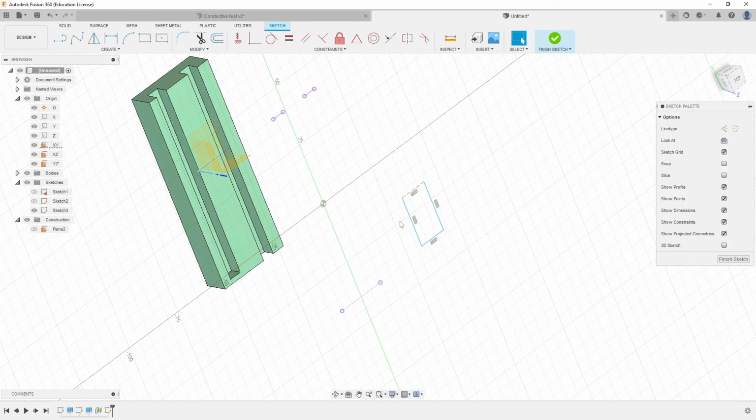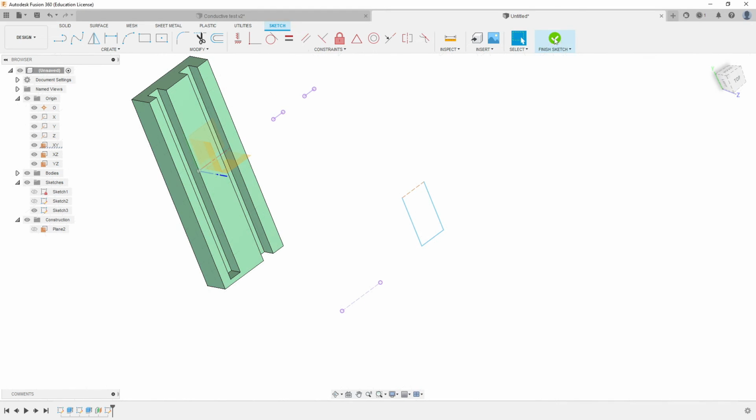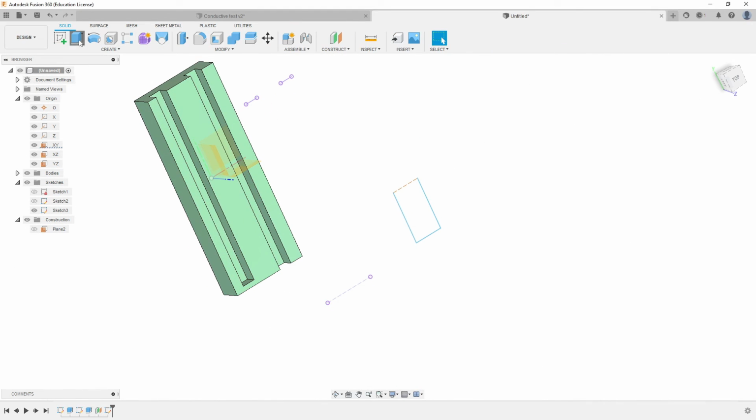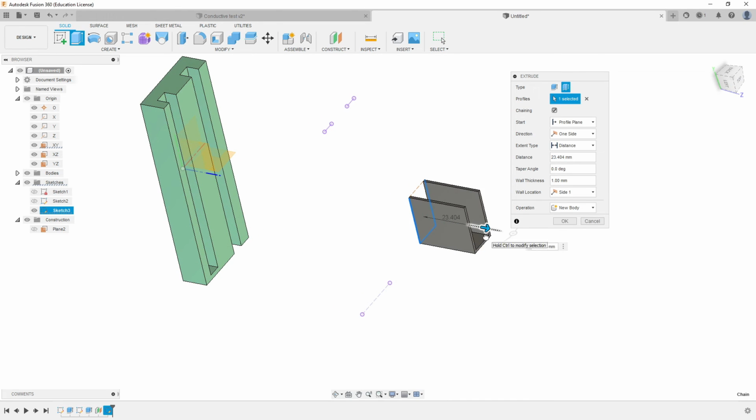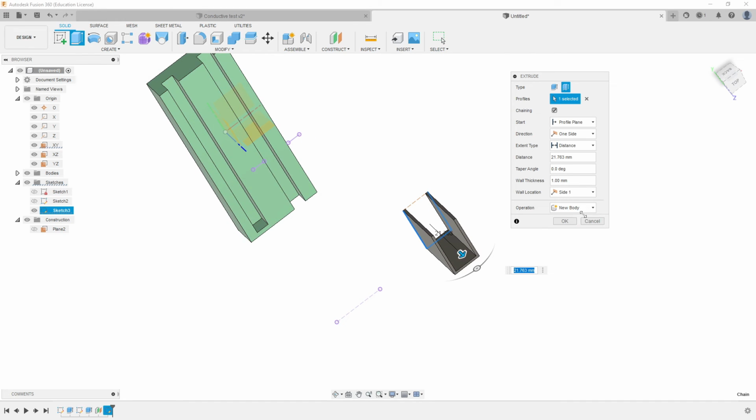Okay. Now, this is no longer a closed profile, so it will not extrude by the typical means, right? It's those two things I just showed you, where I go here. If I'm on this one here, can't do it now because that's not a real element. It will let me do a thin feature, but it will not let me pick that dashed line, the construction element. So you see I could do something like that, okay, which is kind of neat in itself.